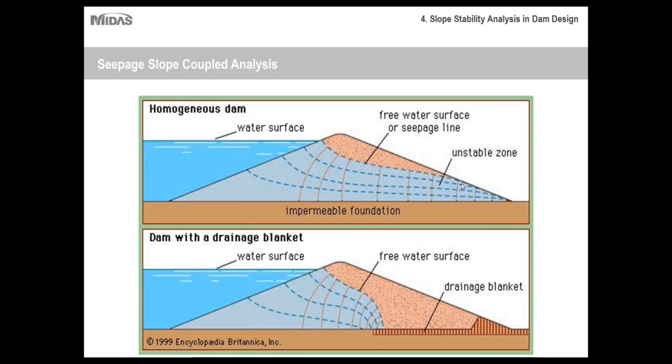So depending on the strength of your materials and the level of seepage, the stability of this side of the dam can be compromised. Whereas if you have implemented a drainage blanket, as shown here, the flow path changes very significantly to the point where all the water is seeping down into the drain and being safely drained out the other side, while maintaining the structural integrity of this slope here. So that's why sometimes a clay core is used just to block the seepage or to slow it down, or a drainage blanket or a drainage pipe is included, just to change the direction of the water. So that's one solution that could be created for your dam.